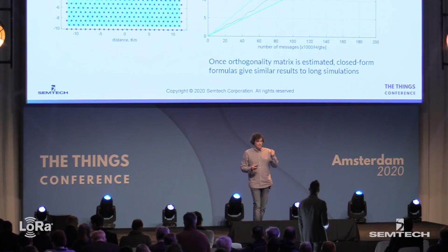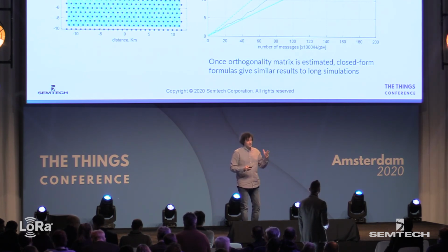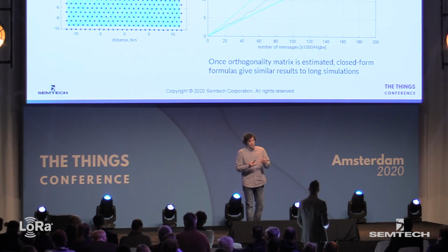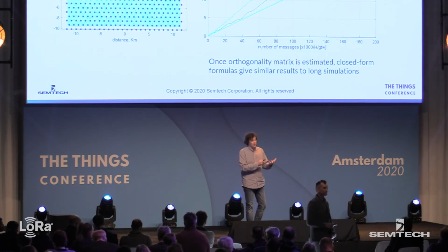This will impact the statistics of the RSSI, therefore it will impact the adaptive data rate, the transmit power control algorithm, it will impact the orthogonality matrix, and then you will be able to compute if the slope is the same. But of course, if there is misalignment, the slope will be steeper, because you will use less spreading factor 7, you will use more the low data rate, therefore you will have longer packets, therefore more collision.